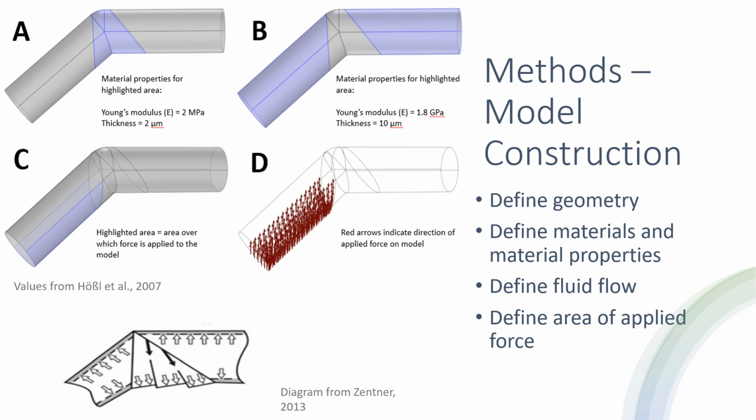I then specified that the entire model was perfectly elastic, so any force applied to the solid would in turn be released. Finally, I specified that the internal bore of this structure was fluid, specifically water, to represent the hemolymph.